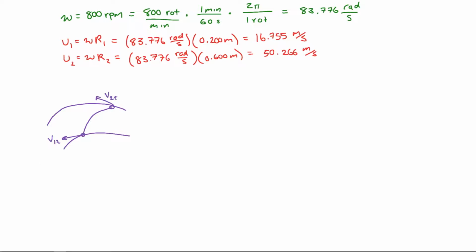So based on Newton's law in terms of open systems, what we can write is basically that the sum of torques is equal to the rate of change of momentum coming out, minus the rate of change of momentum coming in. So this is momentum coming in and momentum coming out. This is how it's defined in terms of a rotational system. So let's first define momentum. Momentum is simply the mass flow rate times the velocity outward minus the mass flow rate times the velocity inward.